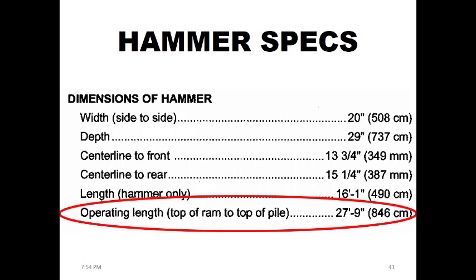So we will not be able to use this particular driver for starting the process of driving the pile. In certain situations, you will notice that for projects, you will need to choose one type of hammer to start the process and another to finish the job. Well, that's because of these technical parameters, but at the same time, you have to relate it to the soil conditions, and in a minute we'll talk about those conditions as well.